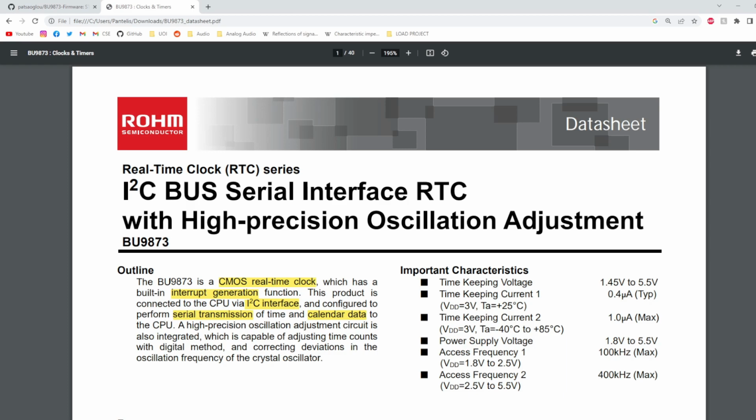So finally, the next thing that you have to look for is a basic configuration section, and more specifically the register maps, because these supply all the register addresses where you are going to write configuration settings and use them to exchange peripheral data.